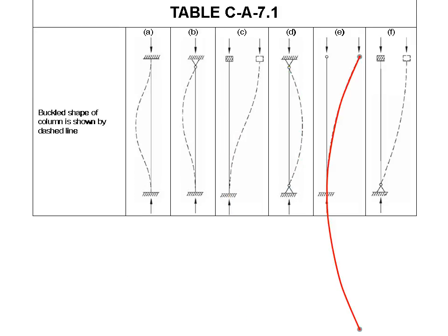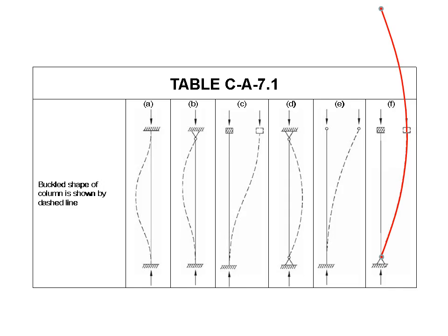The next case, you'll have to shift the table up a little bit so you can see it, but the buckling length drags way down because it's a flagpole column. It's twice the actual length because a cantilever thinks it's really twice as long when it buckles, so K is 2. Now remember that because it'll come up again in a minute. And to finish, we'll slide it up. You can see the buckling length of this column is also really twice as long. And, well, that covers the idealized cases, and I'm sure at this point I've cured my father and mother's interest in K. So we'll move on to the history.